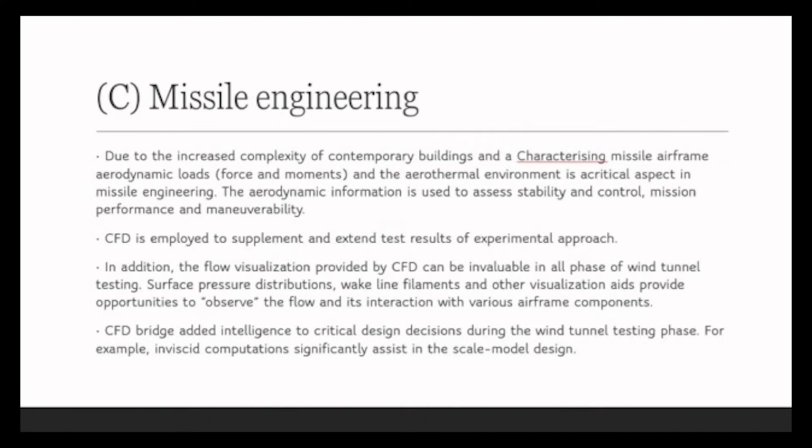In addition, the flow visualization provided by CFD can be evaluated in all phases of wind tunnel testing. Surface pressure distributions, wake line visualizations, and other visualization aids provide opportunities to observe the flow and its interaction with the various airframe components. CFD adds intelligence to critical design decisions during the wind tunnel testing phase. For example, visualized components significantly assist in the scale model designs.